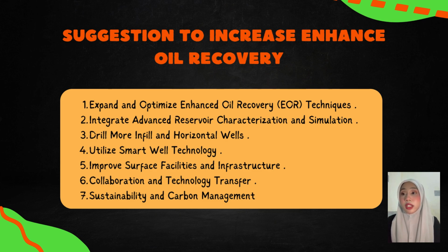The fourth one is utilize smart well technology. Deploy smart wells with downhole flow control valves and sensors to optimize production and injection rates, reduce water or gas breakthrough, and improve sweep efficiency. Also use automated control systems integrated with reservoir models for adaptive management.